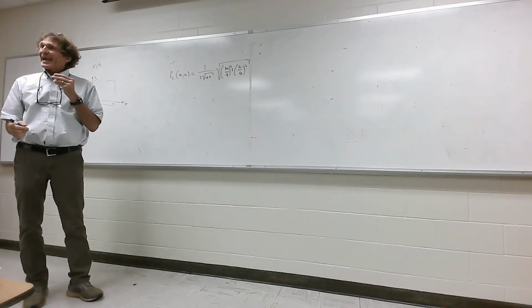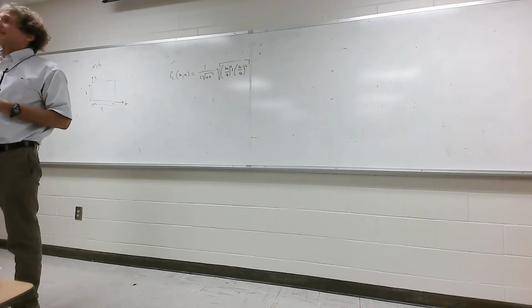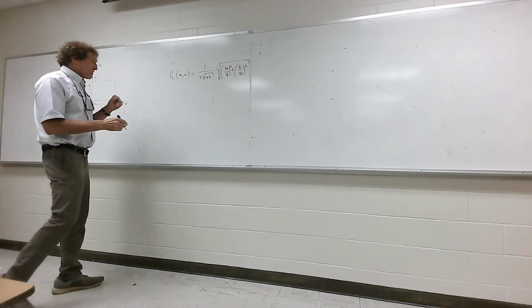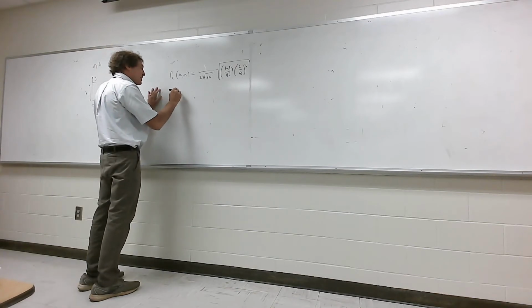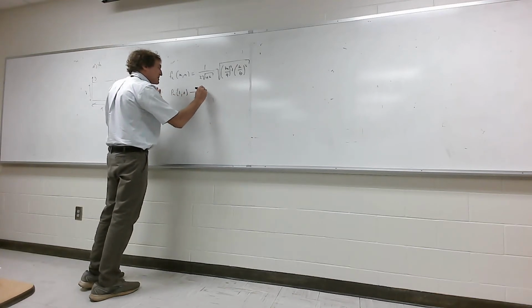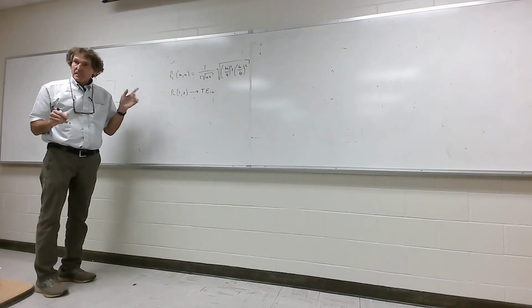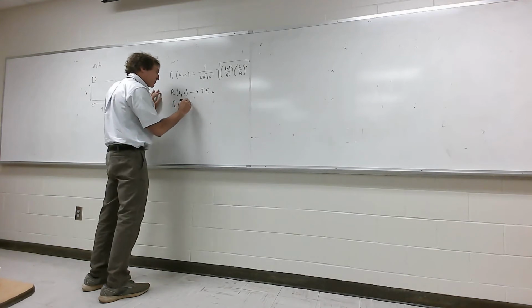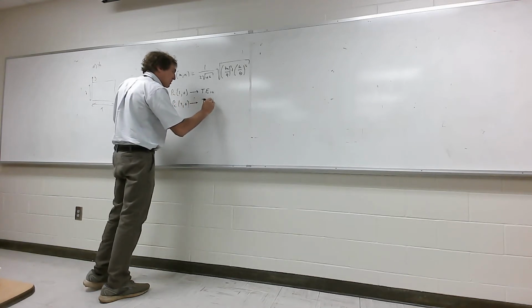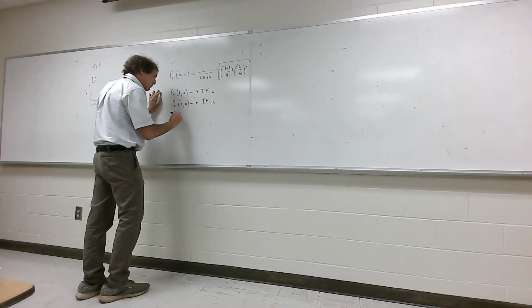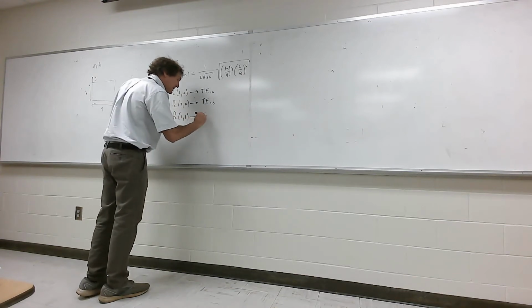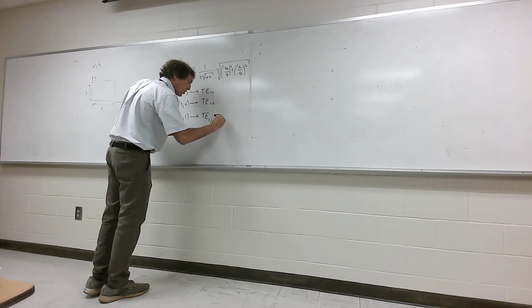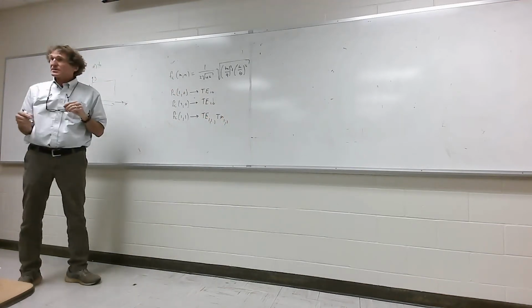But every time m and n, either one is not 0, it can be either a TE or TM mode. For instance, when you have fc10, that can only be TE10. Do y'all follow me on that? When I have fc20, this is the order they usually appear in, that can only be TE20. If I have fc11, that can be TE11, or it can be a TM11. Either one. Do y'all follow me on this?